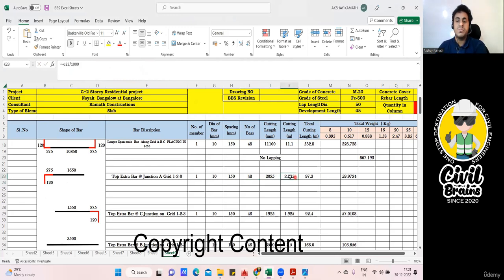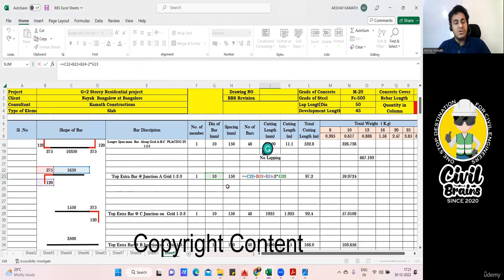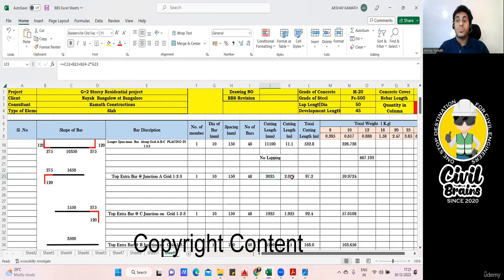Next is very simple. This cutting length will be 275 plus 1650 plus 120, which gives me 2025. And cutting length in meters will be this divided by 1000, you get 2.025. Therefore, total cutting length will be the cutting length of one member multiplied by number of bars into number of members, which gives me 97.2. And since it's a 10 diameter bar, I'll be putting the weight for 10 diameter. So 97.2 into 0.617 comes out to be 59.97. You just reduce the number, keep it 3-digit. Done. Finish.